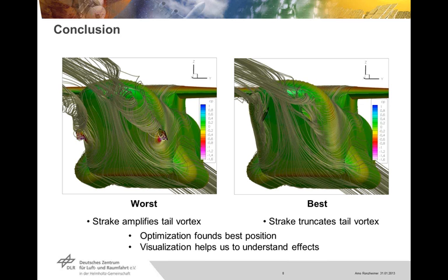There are finally some closing remarks about optimization. It is still an exciting business. Often no one can tell you that your problem has an optimal solution at all. The optimum may be outside the parameter ranges. The CFD solution is not accurate enough, and the cost function becomes noisy due to numerical errors, and the optimization algorithm which you have chosen cannot tackle this. Normally, if I'm not on holiday, it is useful to observe the optimization when it runs, inspect the history and watch the design variables and the surface data. Yes, this can be easily done in Chorus, and I can use it as a management tool for my data.